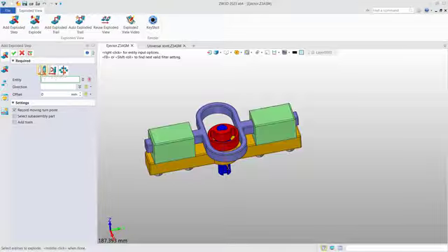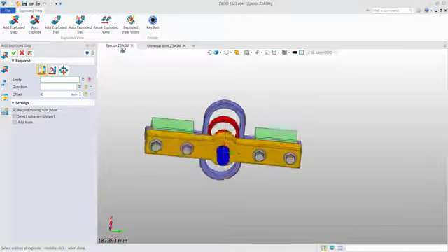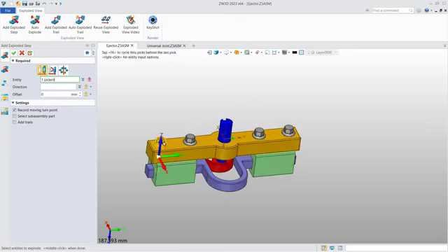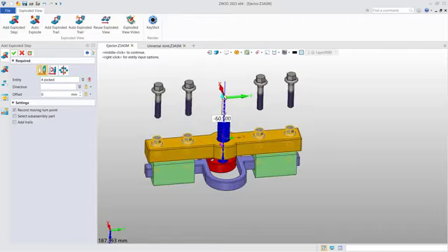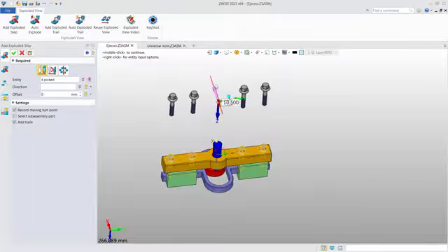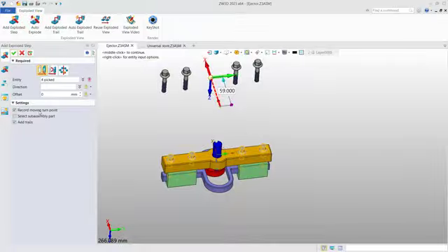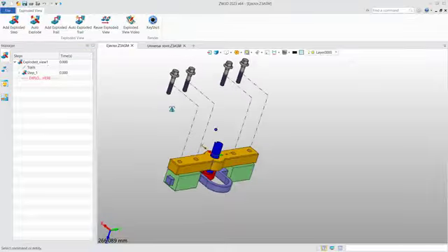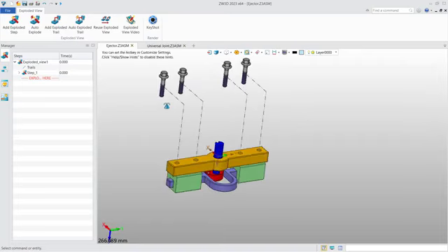For the first one, it's easy to understand. We can just drag the component to add the exploded step. For example, we select these 4 components and we can drag it by the handle. And here you can see, actually we can add the trail, automatically. And also we can record the moving turn points. For example, if here we turn the path here, and it will also record. Okay, now we click OK to check the result. So you can see this is the result. It's pretty good, right?